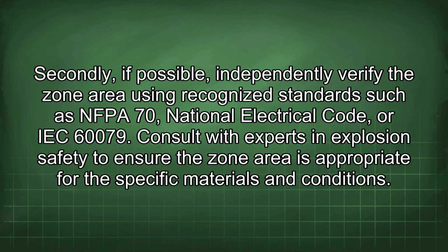Secondly, if possible, independently verify the zone area using recognized standards such as NFPA 70, National Electrical Code, or IEC 60079. Consult with experts in explosion safety to ensure the zone area is appropriate for the specific materials and conditions.